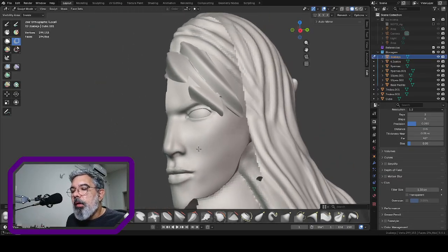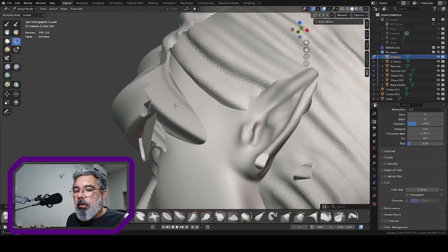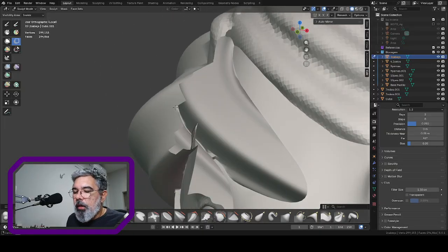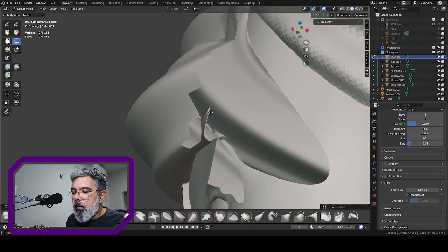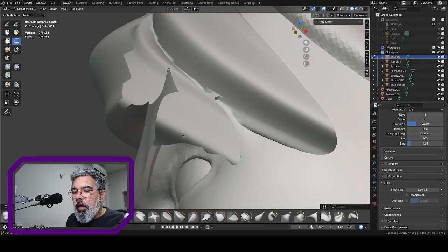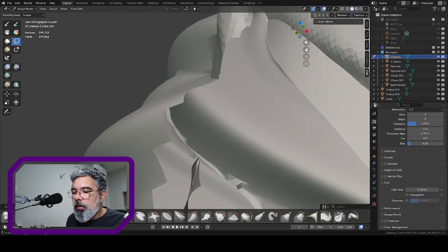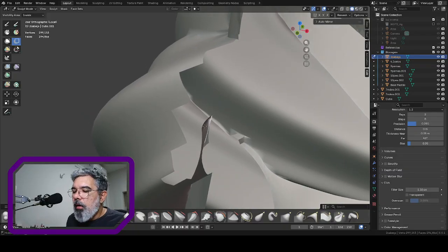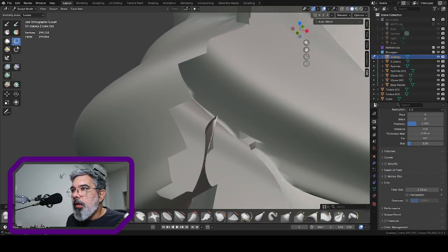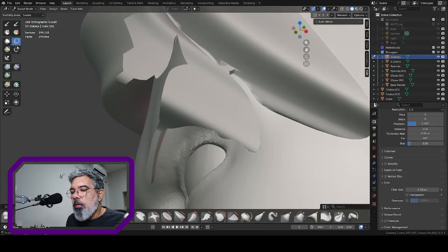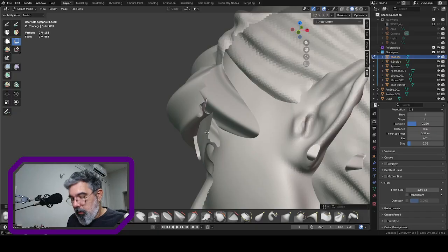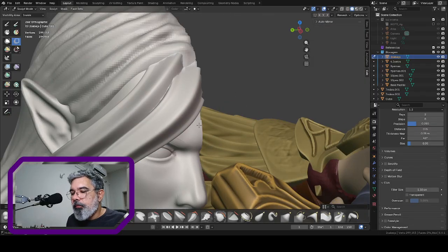that's a very nice shell inside. You may ask me, is there a problem if the mesh stays like this? It's not a real problem, but if you're going to print this model in a big scale, this part here may accumulate some liquid, not solidified resin, and this will be a problem for you if you have a very big one. So how can I fix it? How can I take this part off here?